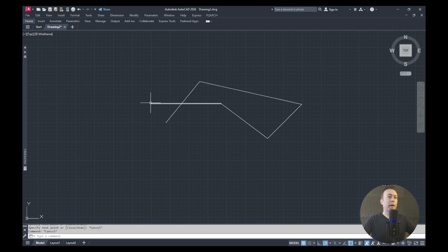Now sometimes you might observe that the mouse cursor, instead of its usual arrow shape, appears as just a simple square. This can occasionally happen. Like when, for example, you enter the erase command. Okay, I'm entering the erase command. Again, how I entered the command isn't important for now. I'll teach you all of this later on. Don't worry. So now I've entered the erase command. When the mouse cursor turns into just a square, it means the software no longer wants you to select a point, but instead wants you to select one or more objects.